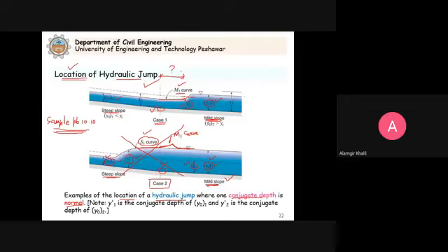So now to answer this question, we have to combine the sections of gradually varied flow that we discussed with the rapidly varied flow. In the location of the jump, we have to combine these concepts. So we have to study gradually varied flow concepts. This we will combine with rapidly varied flow, because you have to determine will the hydraulic jump occur. If it occurs, what is the depth before and after the jump. So you have to apply the concept that we studied in rapidly varied flow.